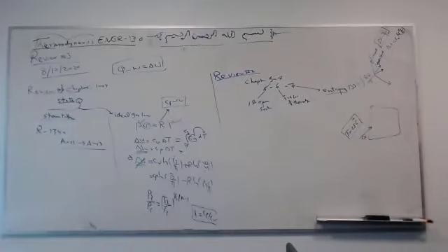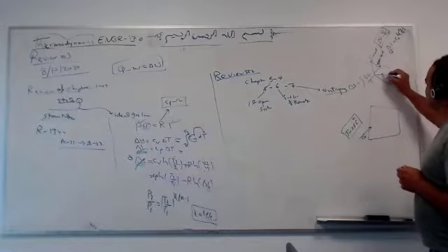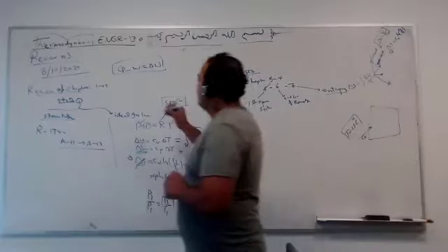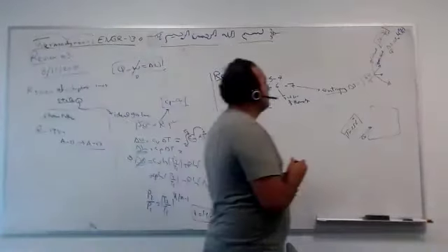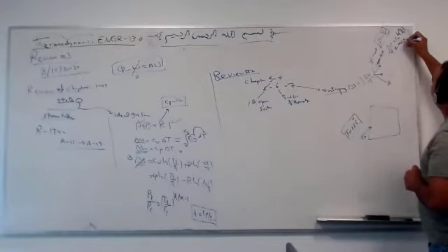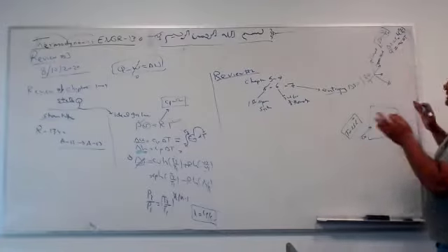So let's go with delta S. Next, it's CV ln T2 over T1. For example, what is the Q here? Does anyone remember for the solid and liquid what the Q is? The heat given in this system, like water warmed from 30 to 70. It has one formula for Q. It's a constant volume, so if you apply this equation, this of course is 0. So what is Q? Delta U? No, it's MC delta T, not delta U.